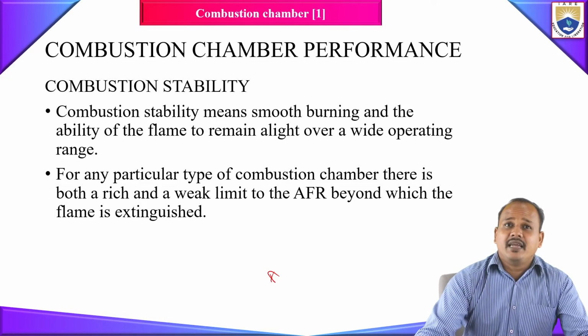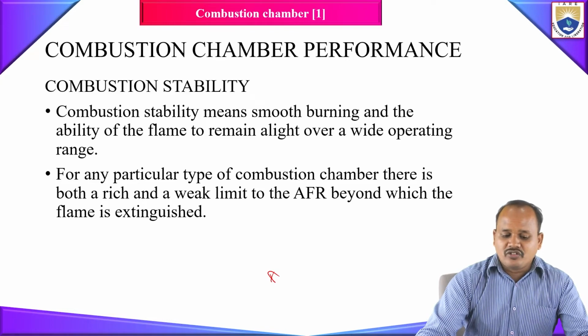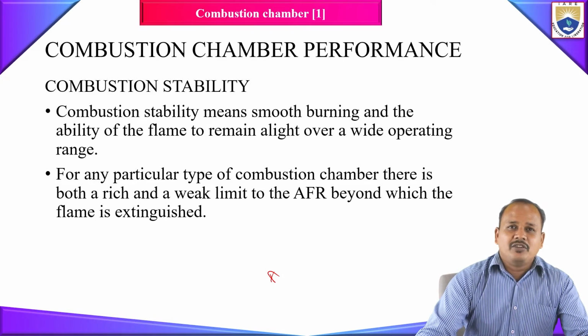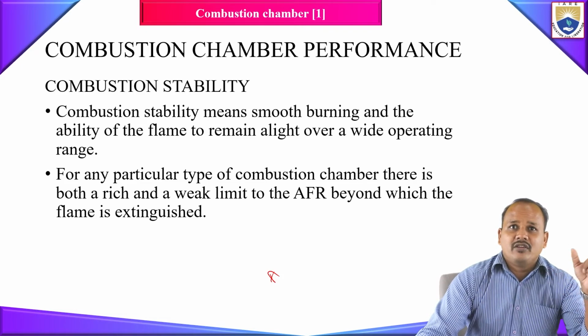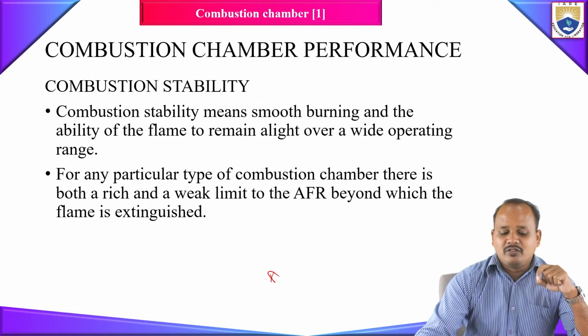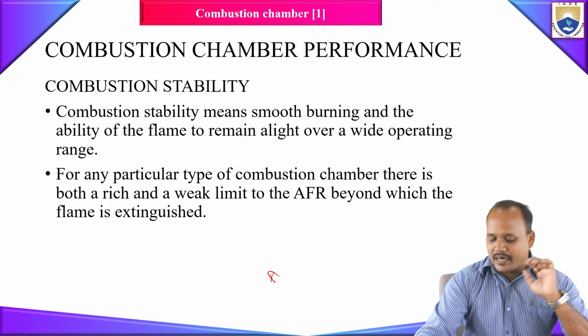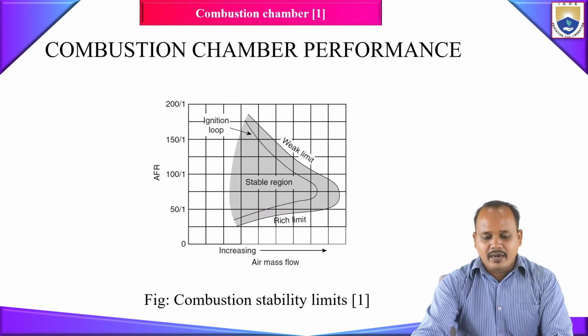Instead, if you pour too much fuel, which will reduce the air fuel ratio, too much fuel will lead to improper or incomplete combustion. That also may lead to the extinguishing of your flames. So you can't have a very lean mixture or a very rich mixture, but the range between your lean mixture and rich mixture should be very wide, so that you can have a wide range of operating conditions.